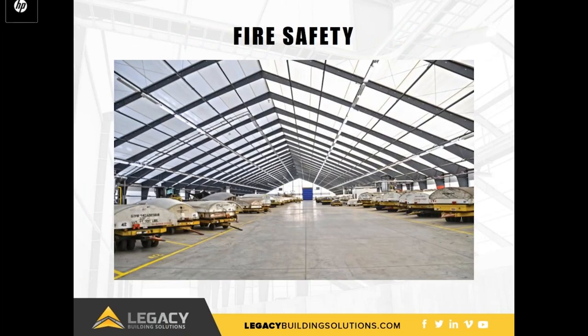Thanks, Nathan. The nature of fabric itself has advantages for many industries. For example, fabric structures are classified as Group 4 buildings by the National Fire Protection Association. In applications such as aviation, NFPA 409 states that Group 4 buildings with less than 12,000 square feet of fire area do not require a sprinkler. Larger buildings require significantly less aggressive sprinkler systems, potentially saving thousands of dollars during initial construction and over the lifespan of the building.